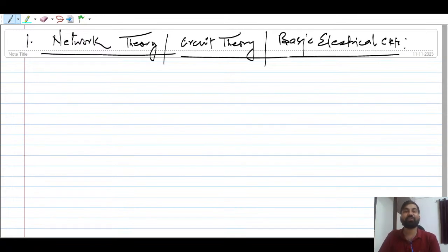And then we'll talk about the number of independent KCL equations. Suppose you have got any network or circuit. We will define circuit in a while, don't worry. Suppose you want to apply KCL over there. How many nodes are there? How can you find that? You just find out the nodes. Then how many independent KCL equations will be there? We always say n minus 1. And then the number of independent KVL equations, and the branch relationships.